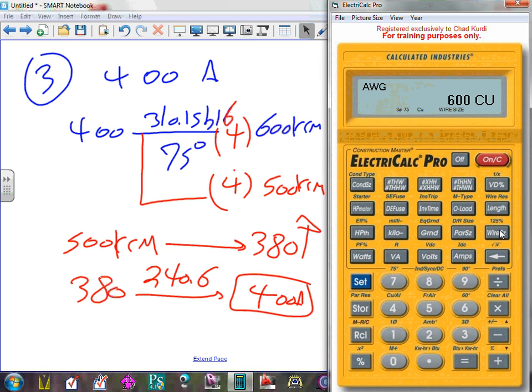Now, Rob, my friend, 99% of the time, this is how you should be sizing. Cable, 4 conductors maximum, and 1 cable for feeders. Done. Don't group things. Feeders. Right? That's the best way to do it. From an engineering point of view, 1 cable, 1 set of cables, and 1 conduit, and shoot it off from point A to point B. Don't group feeders. Bad idea to group feeders. Feeders. I'm not talking about branch circuits.